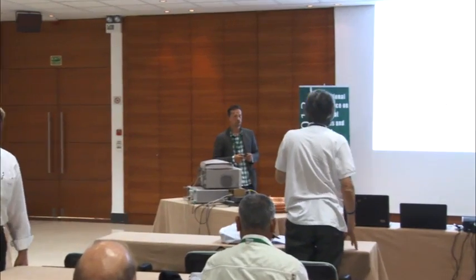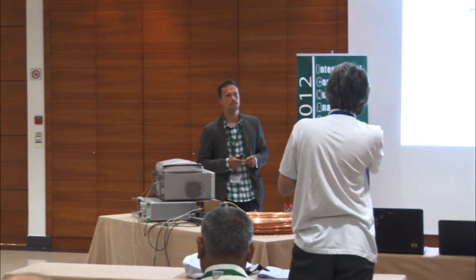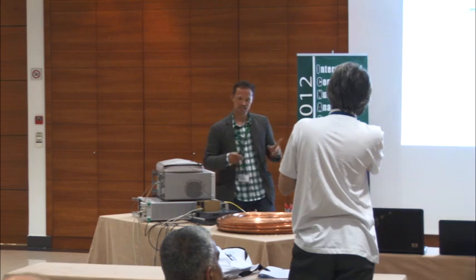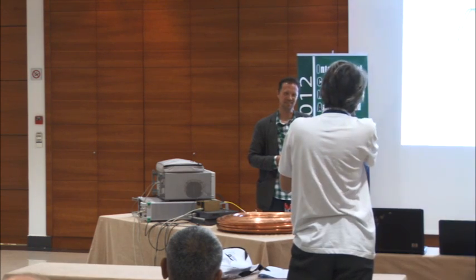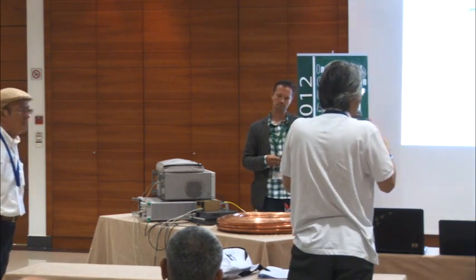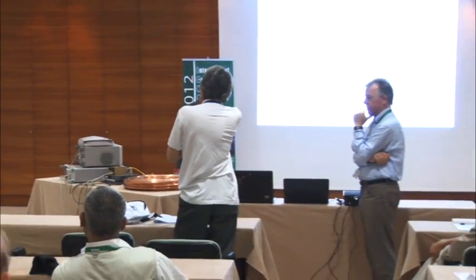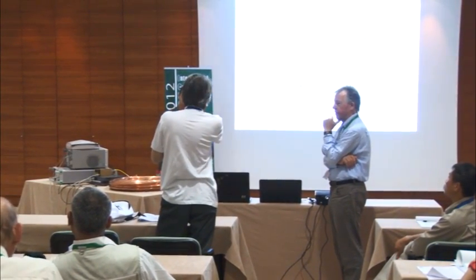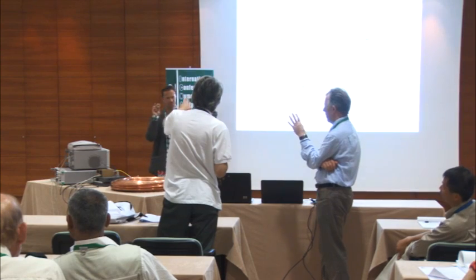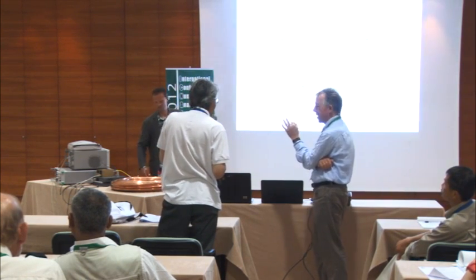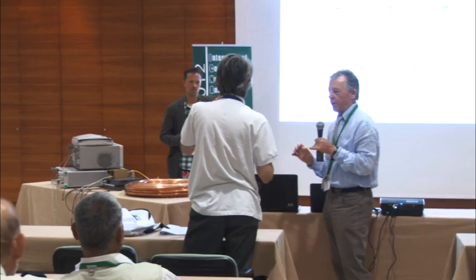So you have mentioned a problem regarding the bandwidth. Is it possible to use this device multiple times? That is something I will cover in future work. You can use the same waveguide for several frequencies at once, because if they are not interfering or making an obstacle to each other, you can use the same 15 meters of guide for maybe 5 different generators at different frequencies. But the problem is that you have to build a barrier 5 times at once. We always have a special bandwidth for each waveguide, a bandwidth of 1 octave only. Otherwise, you have higher modes.